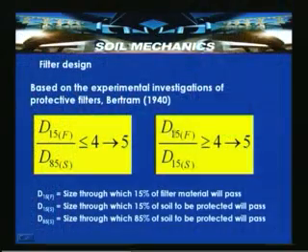And in order to fulfill criterion 2, the ratio of D15 of filter to D15 of soil should be greater than or equal to 4 to 5. By fulfilling these two, if the material has been selected in such a way, then that qualifies as an ideal filter material, and it serves the desired function.